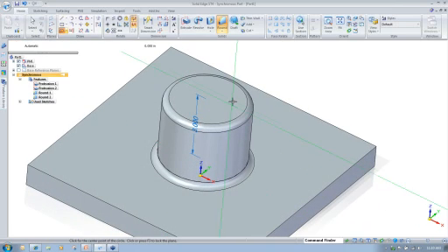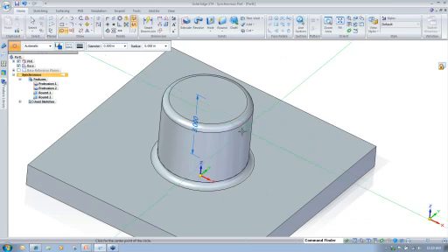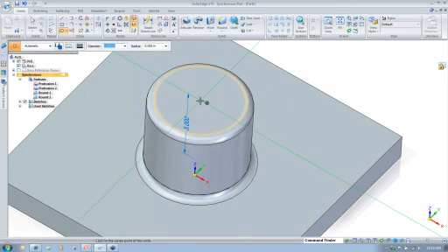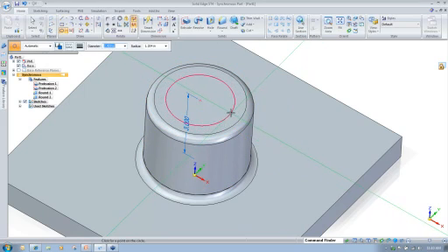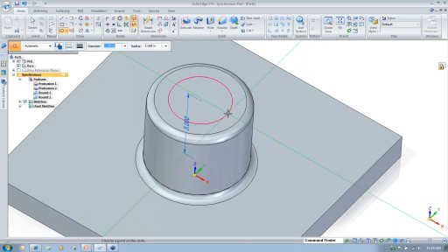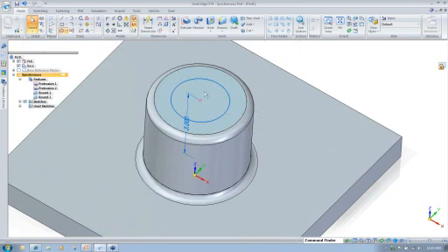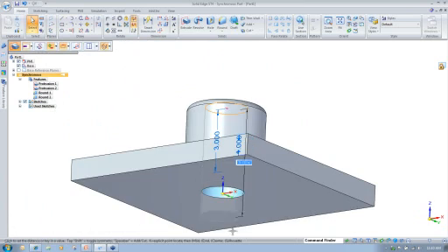And finally, because this is going to be a mounting plate, this is going to be a retention feature. I want to point out here that you can grab existing geometry, and relationship handles will pick up to that existing geometry in the synchronous environment. So for this one, I'm going to put in a 2-inch cutout, and then we can come back, grab the region, and pull it through and make it a cutout.